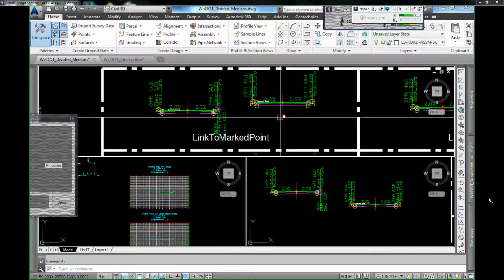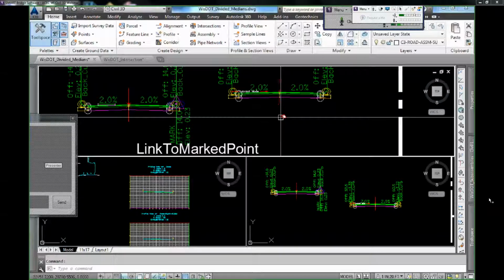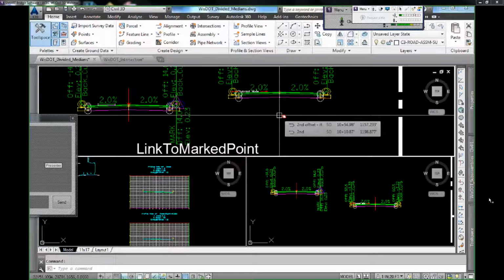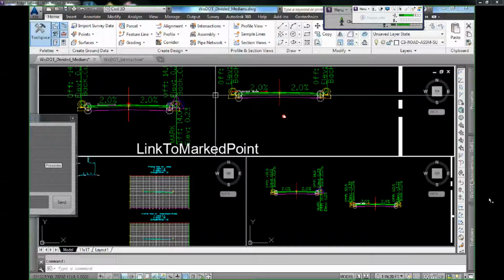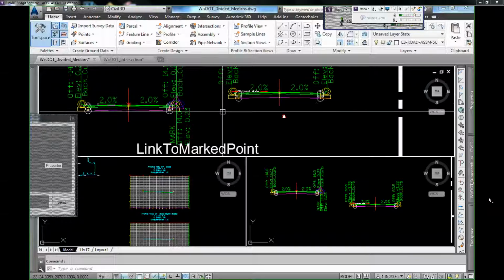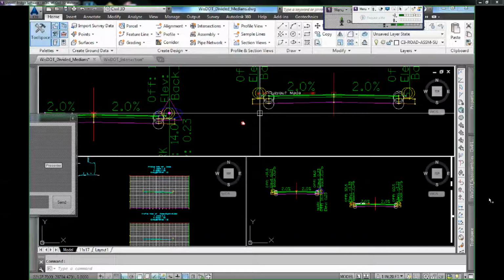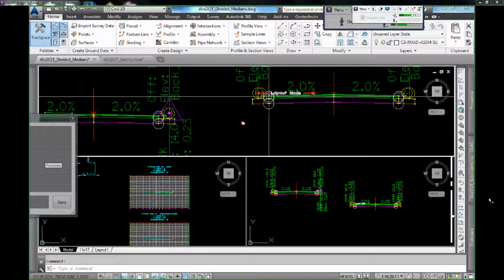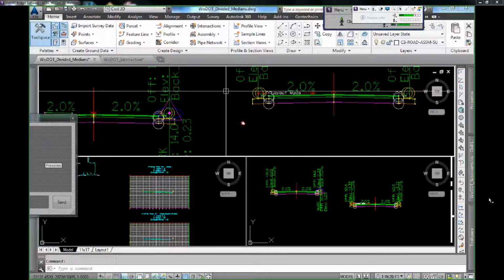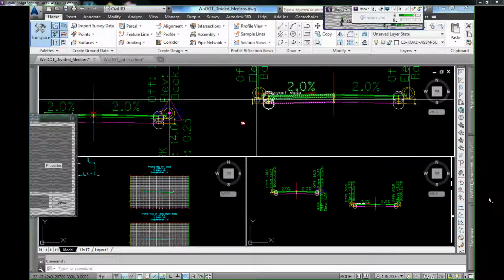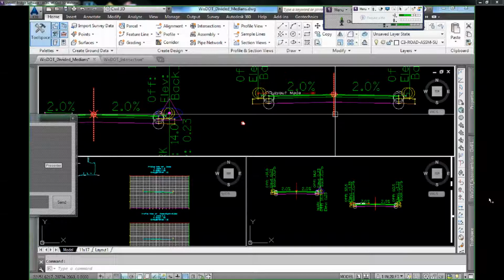Okay. And the other thing is that this will allow this center line to go in and out independently, while the median is going to shrink and get bigger. Okay. We can also, which I'll show you in a little bit, apply targets to the curb here, actually the face of curb, to cause this assembly to stretch inward, or in this case outward, from this offset assembly.